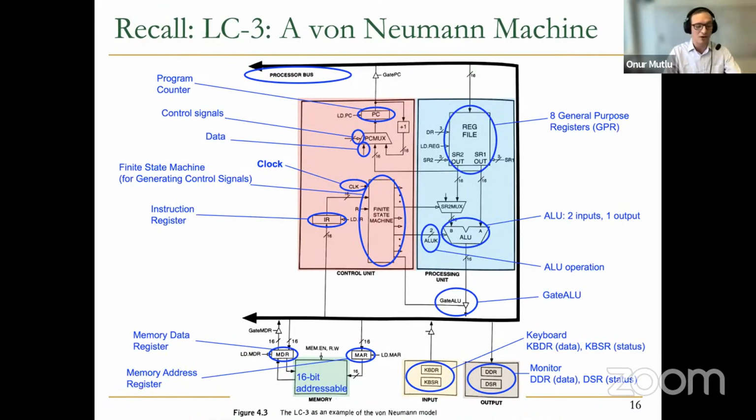So that was our von Neumann machine. I took some time to explain the state diagram to you because I think it's important. And we're going to talk more about it next week, except we're going to assume a very simple finite state machine to begin with when we construct our basic microarchitecture next week. And then we're going to build up to multi-cycle, bigger state machines, and then pipelined processors, and then out of order execution processors, which are very close to how things happen today in a general purpose processor.